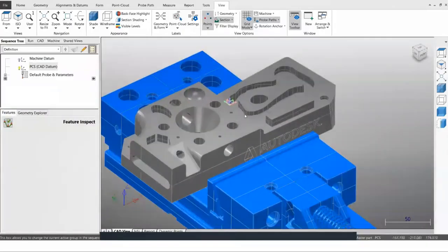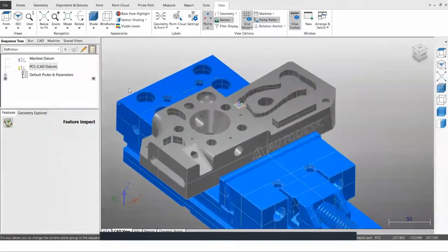So first we'll see what the basic options are. Like I described before, in inspection software alignment is a must. But while you are using this OMV application, and the component is already fixed on your machine, and you have just finished the CAM application on this component and want to measure the geometry feature, then you don't need the alignment because it's already aligned on the machine. So now you have to generate the geometric features only.